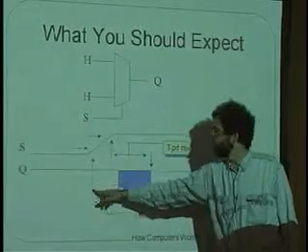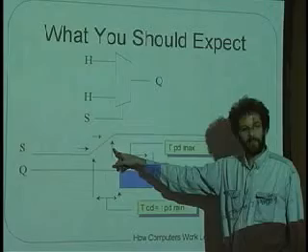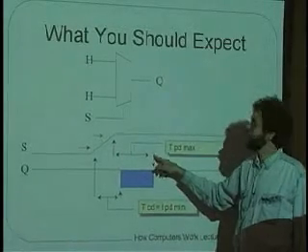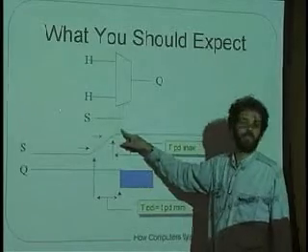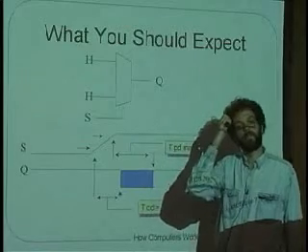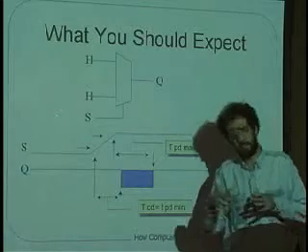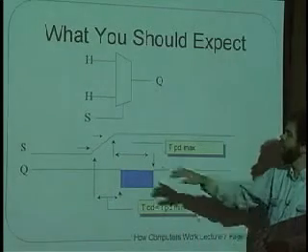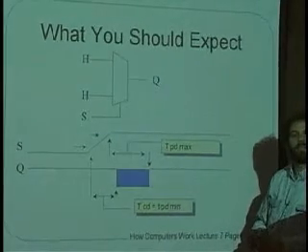So this is from garbage in to garbage out, from new value that's valid in to new value that's valid out. And that's why here we're starting to show you that signals don't transit instantaneously from a 0 to a 1. In fact, they take a little bit of time. And we're just kind of starting to hint at that. And in the class, as we go on and get deeper and deeper into the circuitry, you're going to see how that slope, in fact, comes about in natural circuits.